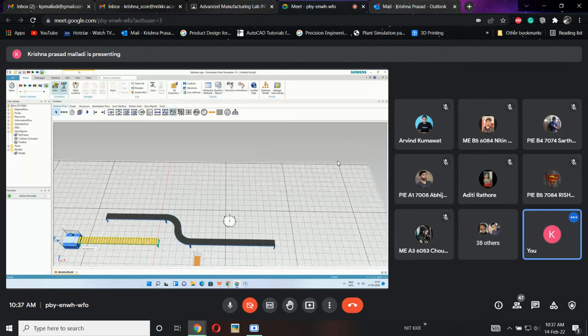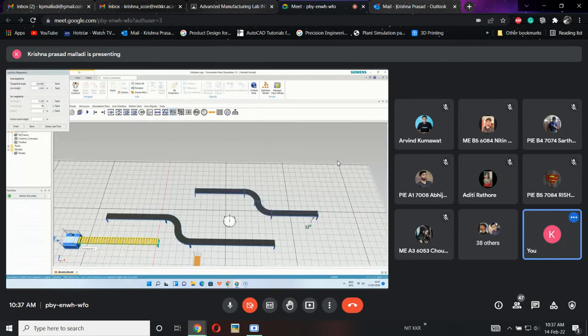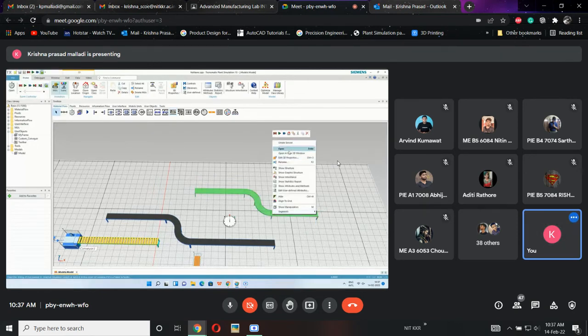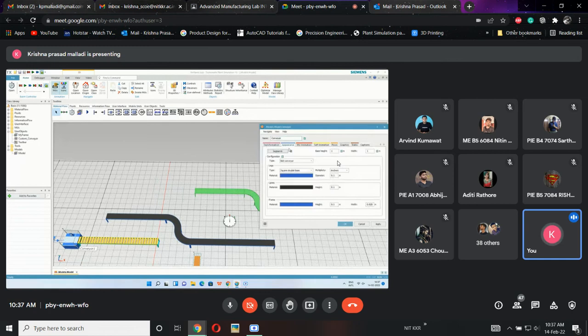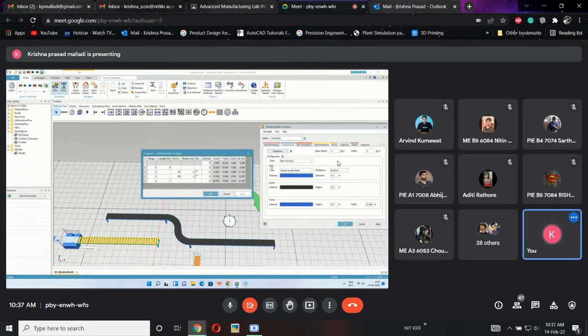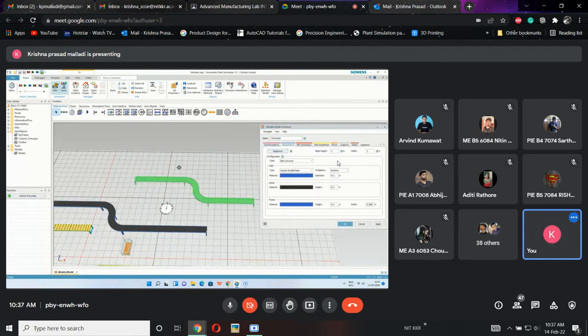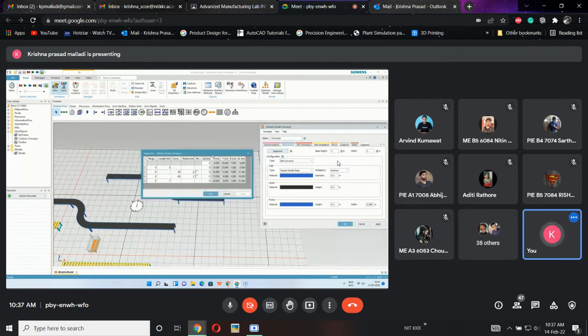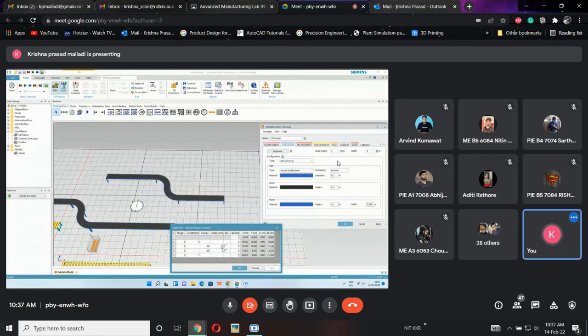This is the easier way. When you compare, it is having multiple frames like this. Now here you will be entering into 3D properties and appearance, segments. In the segments tab, just a second, let me show you. Okay, segments tab. So you will be having two radius values. Here you can alter this, instead of 2 I want 1 radius.